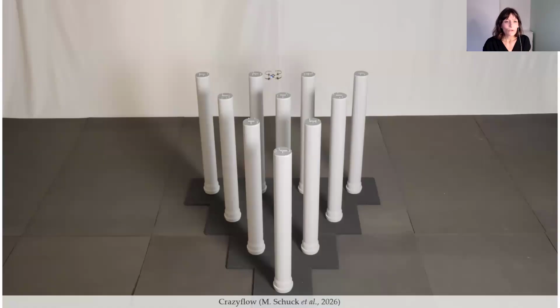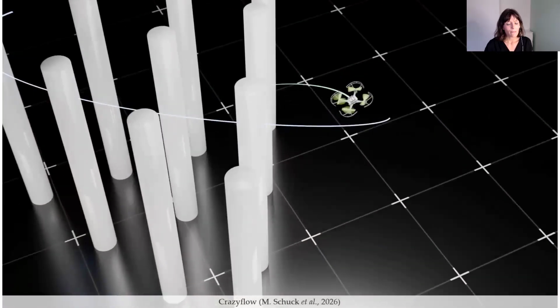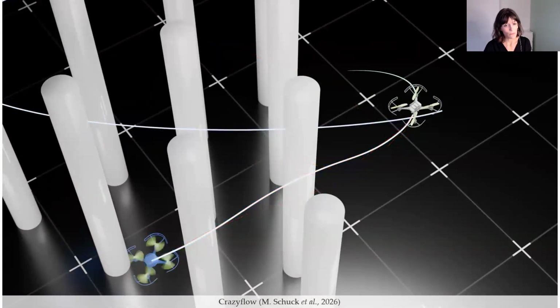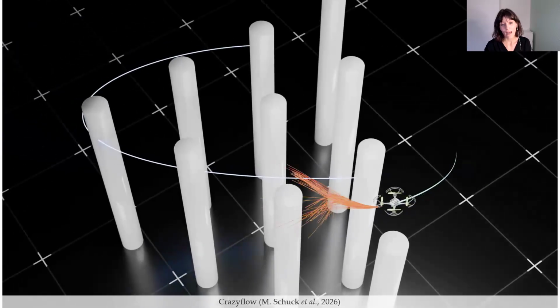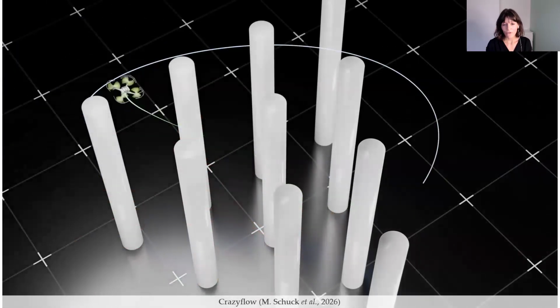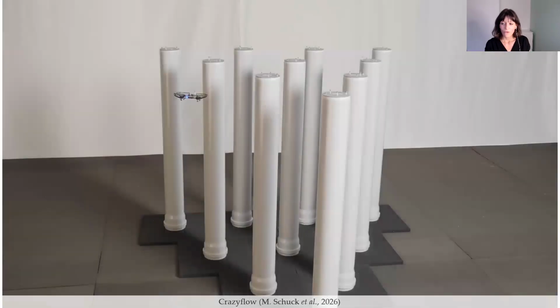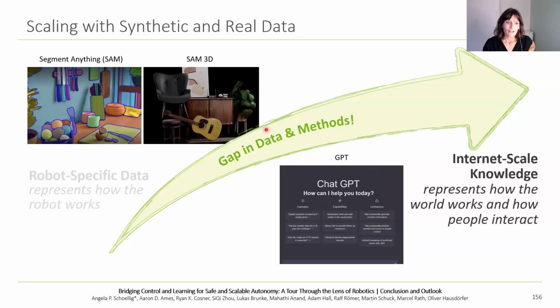And we can do things such as, for example, here we have a planner that doesn't explicitly take into account all these constraints, which would be difficult, but instead we just do a brute-force sampling-based method. Based on the physics of the robot, we can do 500 rollouts in 20 milliseconds and find collision-free trajectories just through massive parallel rollouts, instead of solving the optimization problem in a sampling-based manner, instead of, let's say, a nonlinear optimization.